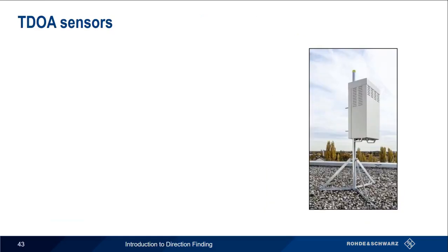All of the previously discussed direction finding methodologies, such as Doppler, Watson-Watt, or correlative interferometry, each require a special type of directional antenna or antenna array. TDOA, on the other hand, is concerned with the time at which a signal arrives, rather than the direction or angle from which it arrived, and thus requires collection and timestamping of all data at multiple points simultaneously. Therefore,